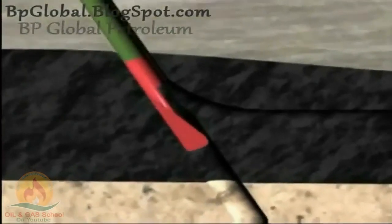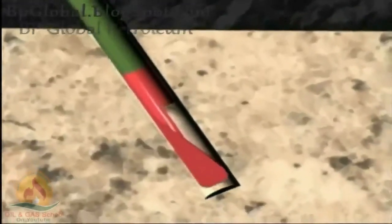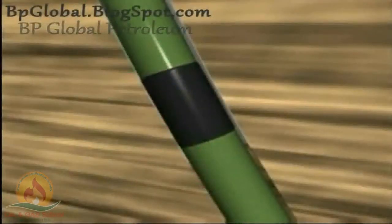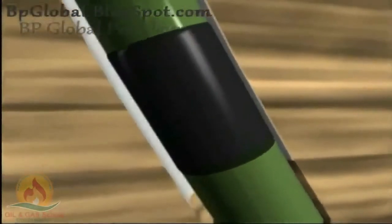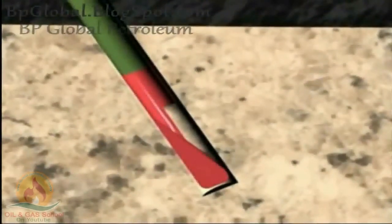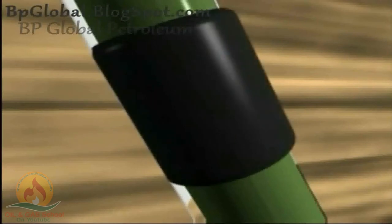Upon completion of the last lateral, the upstock is then lowered to the bottom of the sump area. During the drilling process, we placed in the 7-inch carrier string an annulus casing packer. The function of this packer during the completion phase is to isolate the annulus between the 9 5/8 casing and the 7-inch carrier string. Once the upstock and carrier string are in place in the sump area and sealed in the wellhead, the annulus casing packer, now located just above the 9 5/8 shoe, is inflated and pressure tested for competent seal.